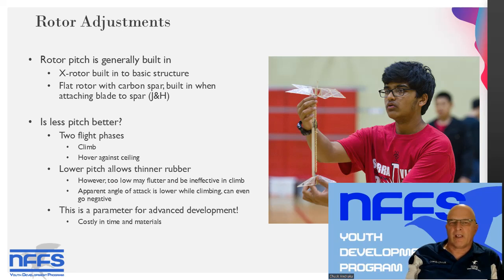I really don't know on the flat rotors like J&H, but the kit is a good starting position. If you want to adjust your pitch from there, build another set of rotors with a different gauge to set your pitch and try that out. Lower pitch will allow thinner rubber, but it might flutter and be ineffective in the climb. So consider the rotor adjustments to be an advanced development project.